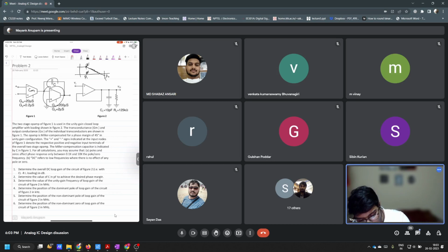And P1's location, we say that it is because of the amplification of this capacitor C by the Miller factor. That we say, but strictly speaking, that is not the case. But all these approximations hold as long as this transconductor GM2's unity gain frequency is larger than the unity gain frequency. This is not strictly true because it is indeed a frequency dependent gain.